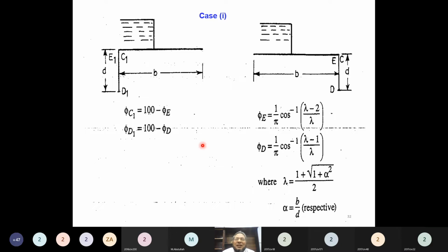अच्छा चलें, मैं अब ये सवाल आपसे किसी और तरह पूछता हूँ। What about E1, how much should be the pressure head, uplift pressure E1 पे कितना होना चाहिए? So maybe, Sir, we can find equal the pressure at E1 by difference of phi C1 and phi D1. नहीं यार, please listen to my question. How much should be the pressure head at point E1?